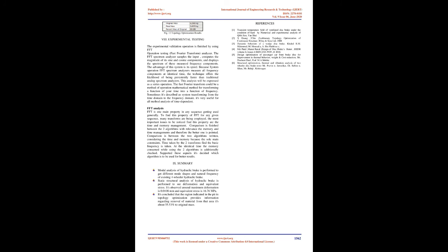The advantage of this system is its speed. Because FFT spectrum analyzers measure all frequency components at the same time, the technique offers the possibility of being consistently faster than traditional analog spectrum analyzers. This analysis can be expressed as a series operation.